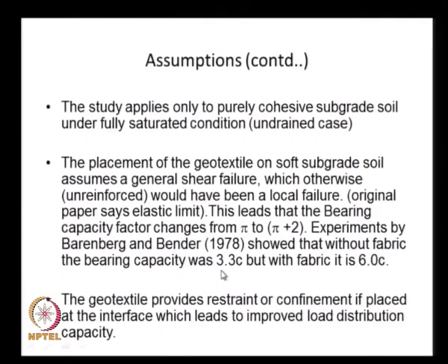They have shown that the bearing capacity of undrained clay soil is 3.3 Cu when there is no reinforcement, and when there is a fabric reinforcement placed above the clay soil, this bearing capacity factor increases to almost 6.